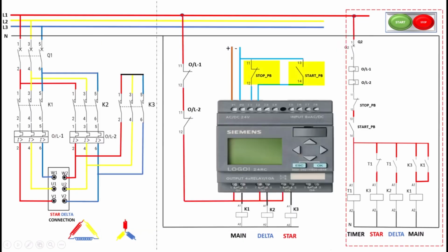Okay, now start and stop buttons are digital signals going into the PLC, which then decides when to activate each relay based on the logic we've programmed. It's a similar approach, but gives us way more flexibility for controlling and monitoring the system. By setting up the PLC this way, you'll get a clear view of how the system functions.